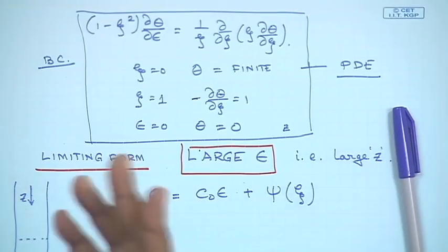This is a condition which needs some explanation, so I will try to explain that to you. As the fluid starts to move in the z direction, its temperature will progressively increase. But after the fluid has travelled a certain distance, the shape of the profile, which is given by its functional dependence on r, or in dimensionless form zeta, will remain unchanged. Only the values will keep on increasing, and that too linearly with z.